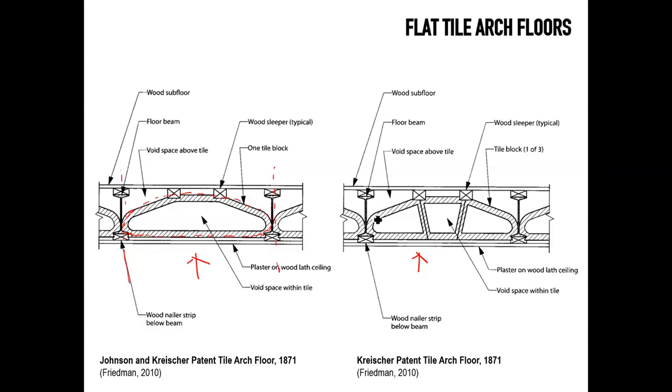So a flat arch, if you recall, is an arch that is not quite an arch. It's a flat lintel structure, but it's using some of the same principles of an arch by having all the bricks or sometimes masonry voussoirs cut in such a way that their shape can push the thrust sideways.